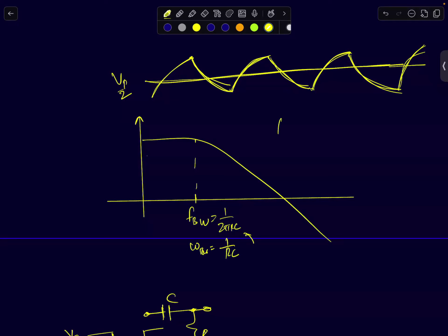If I tell you that the fundamental frequency, see, it's a pulse signal, right? If it's a square pulse signal, it will only contain odd harmonics. If the duty cycle is 50%, a square pulse signal will only contain odd harmonics. And I gave you an intuitive reasoning for it.